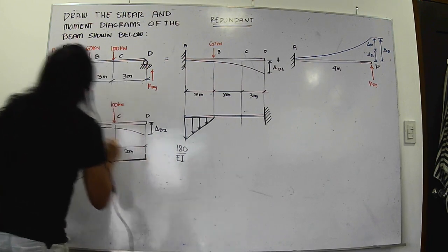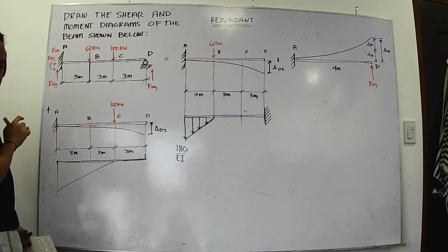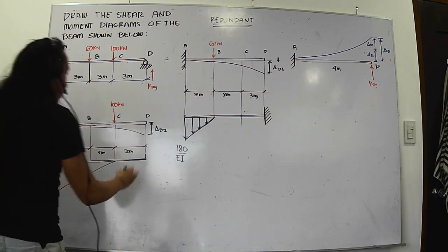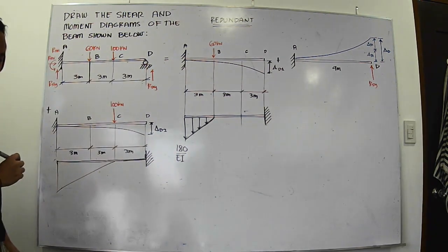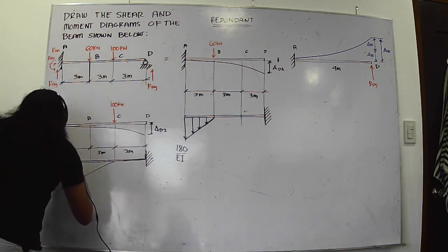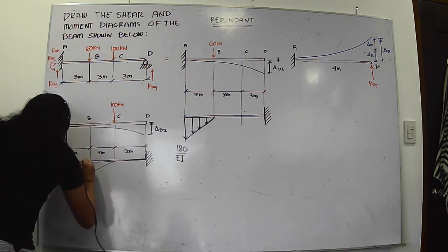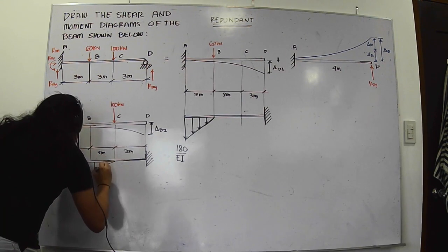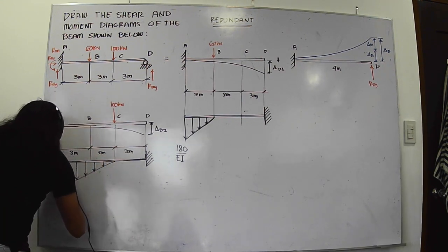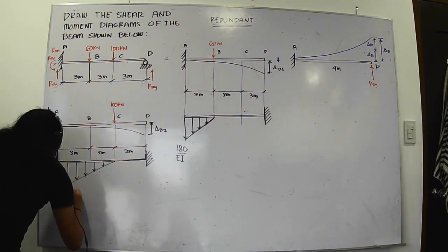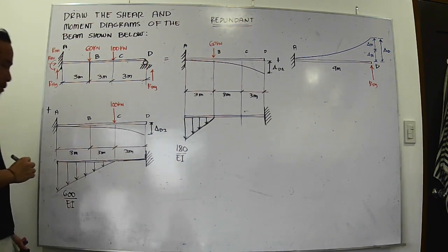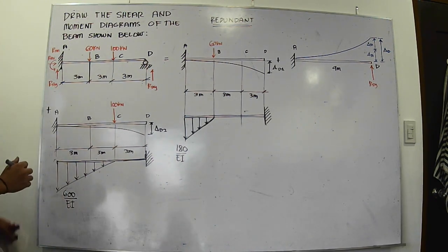Same process. Fixed end becomes free. Free end becomes fixed. So, ano siya? Ako rin siyang drawing and then nag-load. Okay? All of this is going down. And this is 100 times quantity is 6. That should be 600 over EI. Okay? This is our conjugate beam for this.